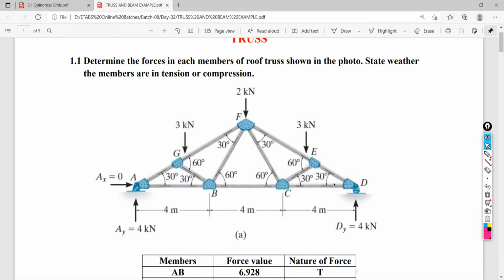There are so many assumptions that we have discussed: loads will be only at the joints, all the sections are of uniform cross section, all the elements have uniform cross sections, all the members are connected at their ends only. So it will not be right to take the element from this point to this point directly. If you think it is along one line, why are we going to break it at this point? Why are we not taking it continuous up to this end? So it is the assumption. It is a real practice where we consider the element from end to end and point to point.